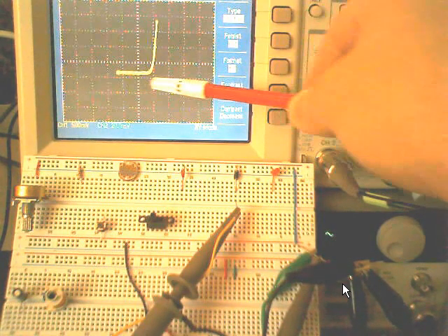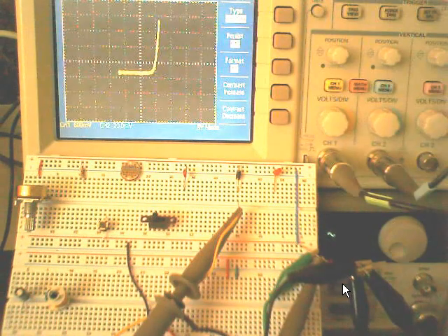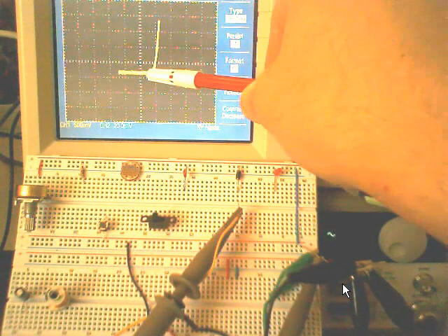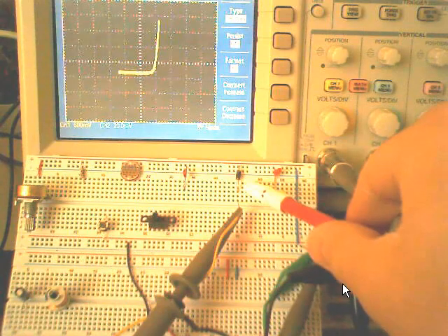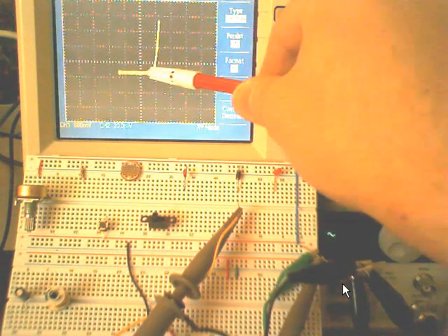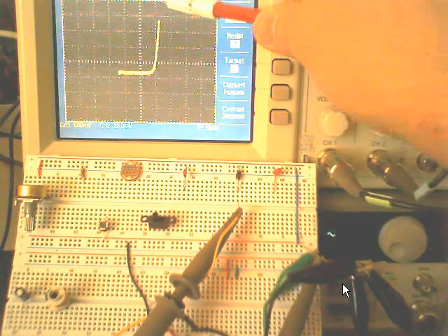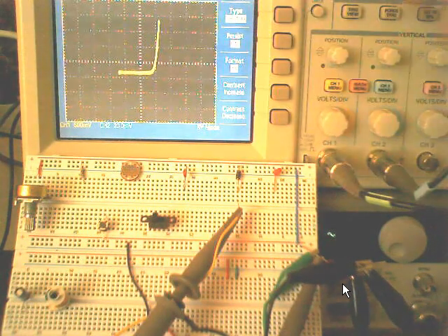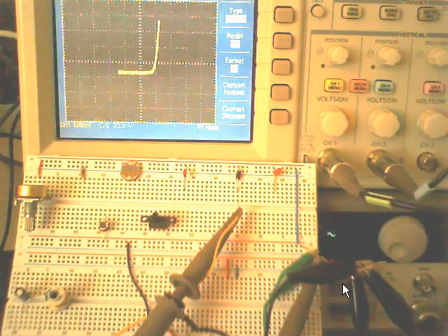It shows an open circuit. If you apply small voltages smaller than a threshold, a diode is an open circuit. But if you exceed some voltage, the current will immediately increase, and it's, as you see, approximately short circuit. It's a very, very low resistor now.